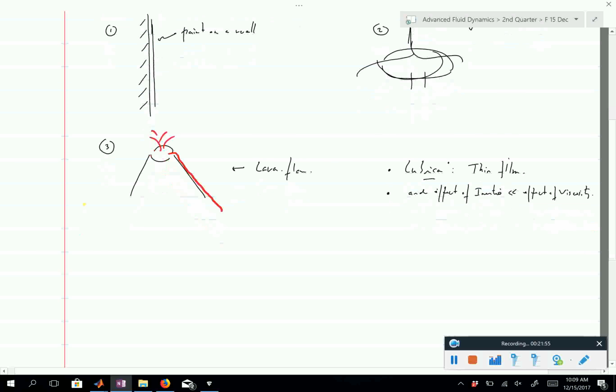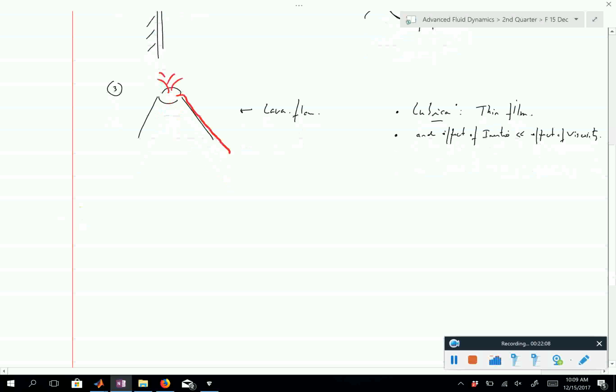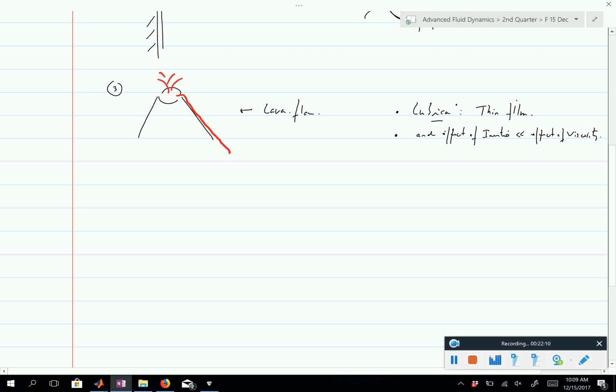Now, usually this is always what is characteristic of the Reynolds number, and you'll see that for lubrication theory it will also look like a Reynolds number, right? But it will be the Reynolds number times the ratio of length scales. So there is a Reynolds number in there, but it's not just the direct Reynolds number. So you have to be a bit careful about how you determine whether or not you are in the lubrication regime. So now number 2, we'll simplify the Navier-Stokes equation in the lubrication limit.